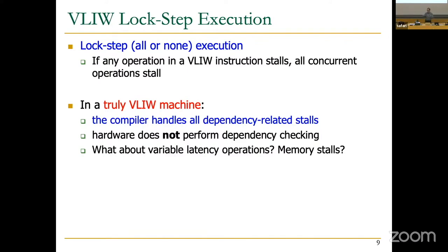There needs to be some hardware support to stall the bundle if the compiler didn't predict the latency correctly, for example. And this becomes even worse. We're talking about a multiply. Multiply is not that bad. Let's talk about a load. Now, once we go to memory, let's say all hell breaks loose, right? And that's true with modern machines. A load instruction, how long does it take? We're going to see the memory hierarchy soon, but the compiler may assume it's going to hit in the L1 cache. We're going to talk about all of those soon.